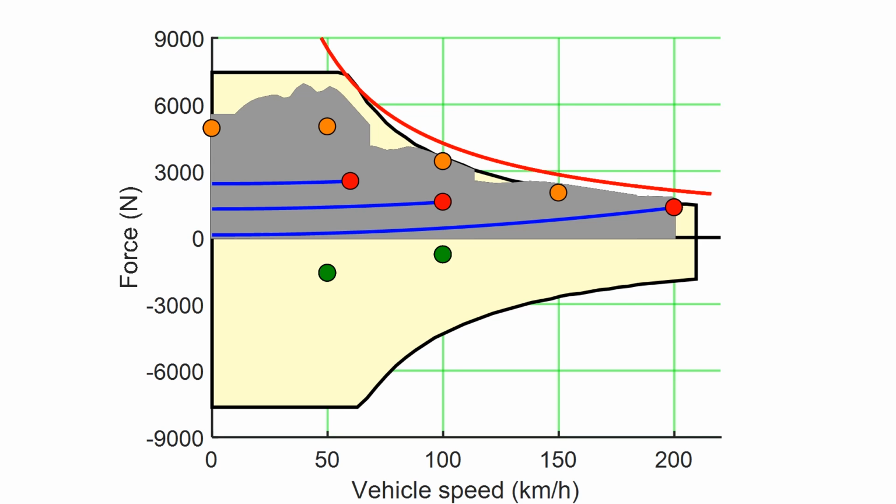This is because an electric machine can increase its torque in just a few tenths of milliseconds, while a combustion engine often requires several hundred milliseconds up to about 1 second to build up full torque. Additionally, this electric powertrain never needs to change gear, so it would provide a much quicker acceleration response in many cases.